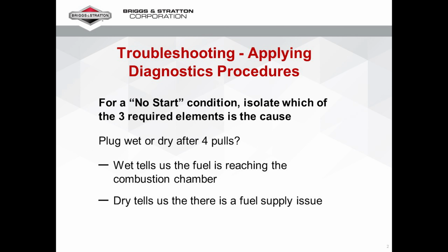In this video, we are going to cover how to quickly drill down through carburetor and fuel system troubleshooting to make a call on a repair with high confidence. The first thing we need to do is apply some diagnostic procedures to help isolate the problem better. The first hypothetical situation is that we have an engine that is a crank no start condition.